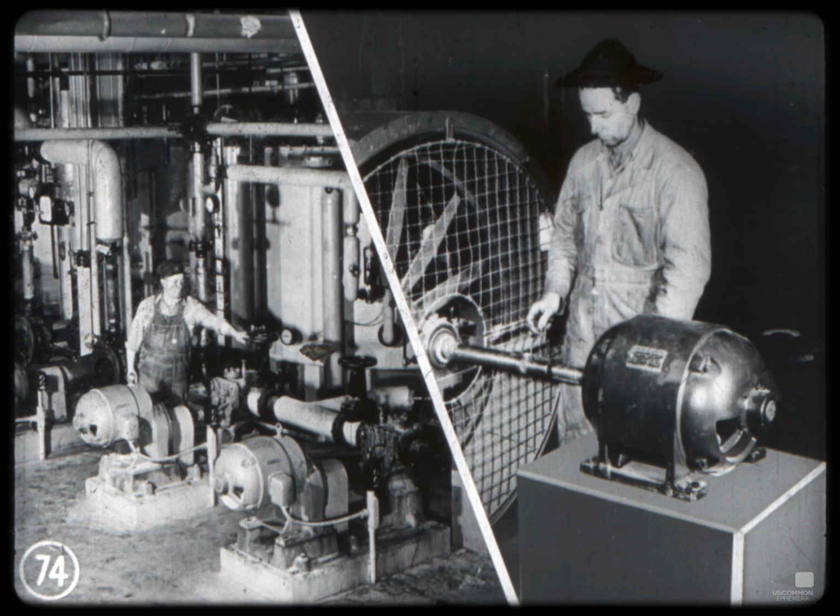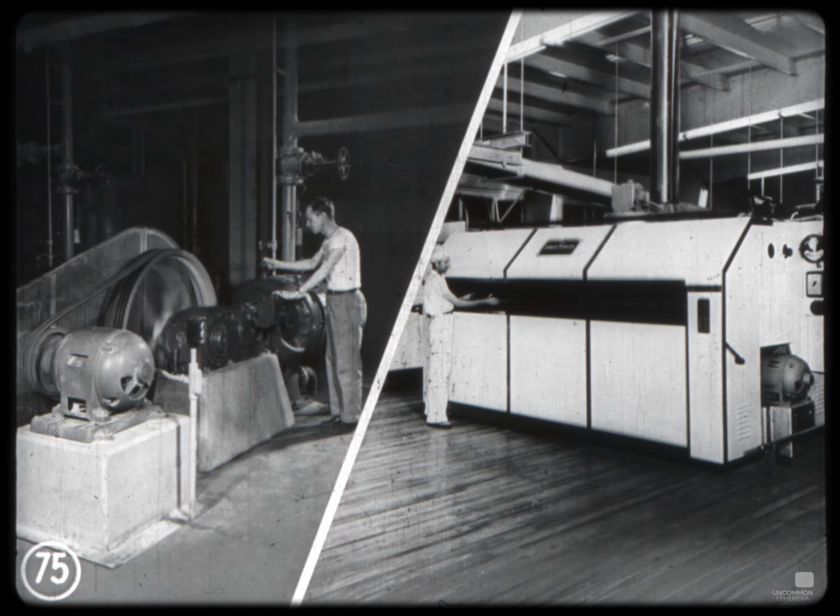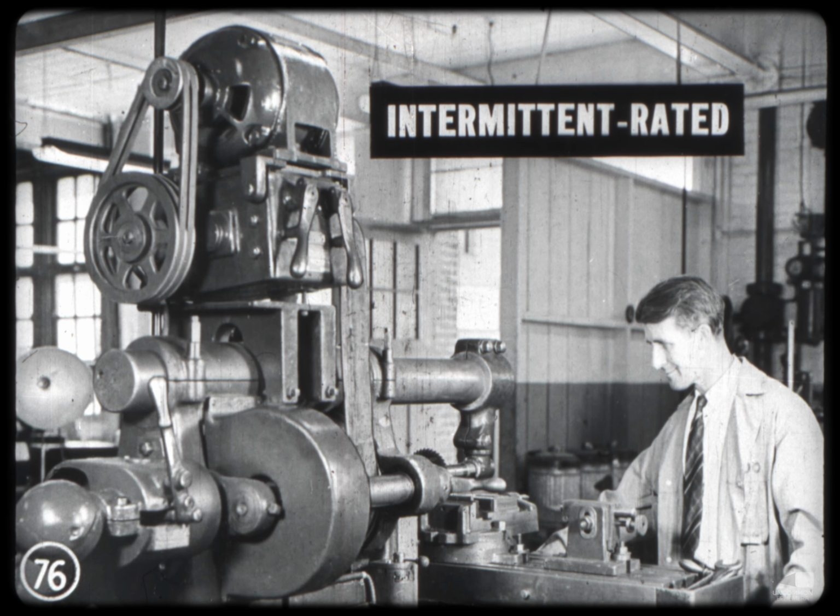Pumps and fans, for instance, usually need a continuous rated motor, as do compressors, conveyors, and other machines which run at full load for long periods of time. Not all machines, of course, do run continuously at rated load, and when this is the case, it may be that the motor can be intermittent rated. In other words, rated on a short time basis.